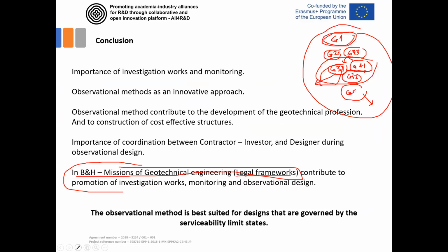Once again, the observational method is applicable for designs that are governed by the serviceability limit state, so where we are discussing displacements, and not problems where some failure can occur in a very short period.